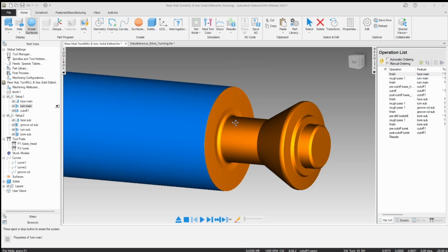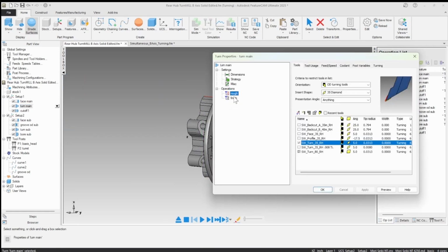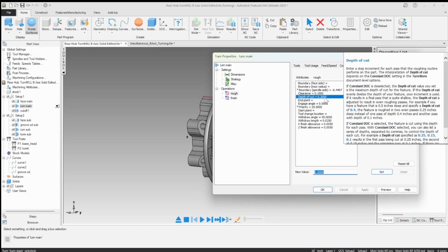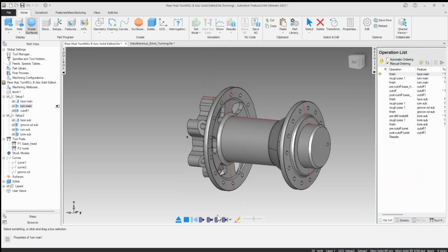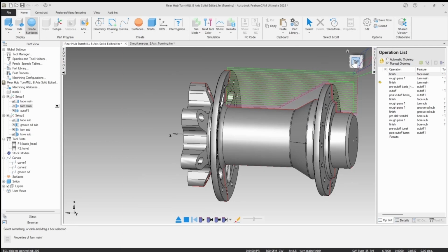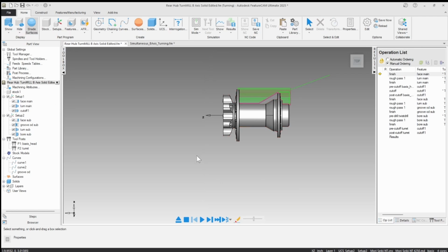All right, so there's just that little bit of an undercut there. So just as a reminder, your depth of cut, you can set in your attributes or your configuration for your attributes and adjust, but I'll just adjust this toolpath just to kind of show you. We'll preview both of these. Remember, the preview mode is really handy. So you can see just the toolpath, and in this case, I want to see both. You can see how the tool is able to reach up under there now. Okay, so get out of preview, and let's take a look at some more of this.